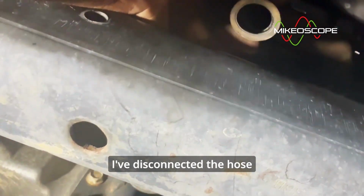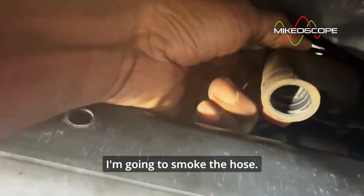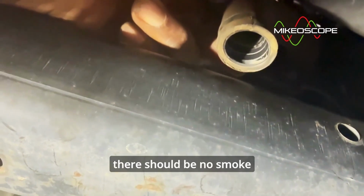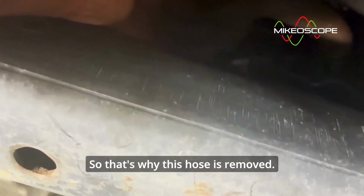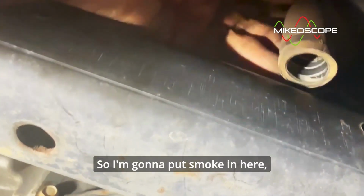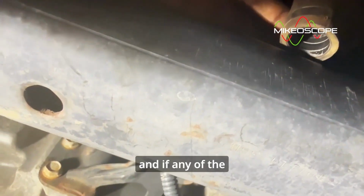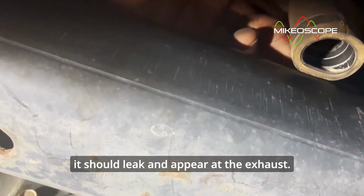So now you can see I've disconnected the hose that goes to the pump, and I'm going to smoke the hose. With the valves closed, there should be no smoke coming through the exhaust. So that's why this hose is removed. I want to see if any of the valves aren't closing properly. So I'm going to put smoke in here. And if any of the valves isn't closing properly, it should leak and appear at the exhaust.